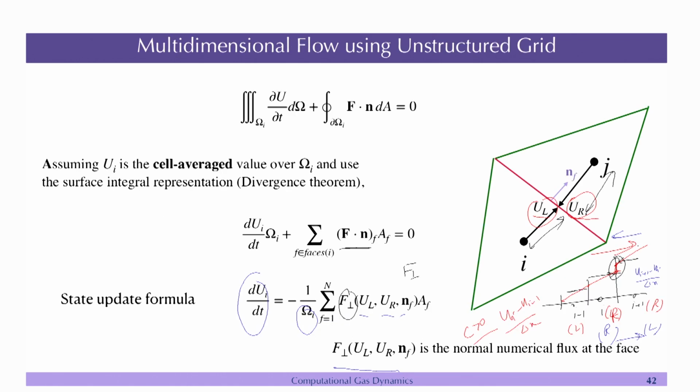So you are working here. Just like we had this linear variation, you will have variation across the cell also, right. If you use the constant value in the cell, then you will get only first order accuracy, and that too the accuracy will decrease because you are using an unstructured grid. So, you will have to have a linear variation in the cell also. That process is called reconstruction, just like we discussed the slope limiters. So, we will limit the slope and we will see.